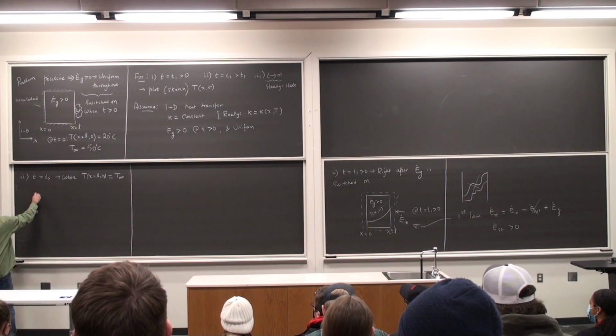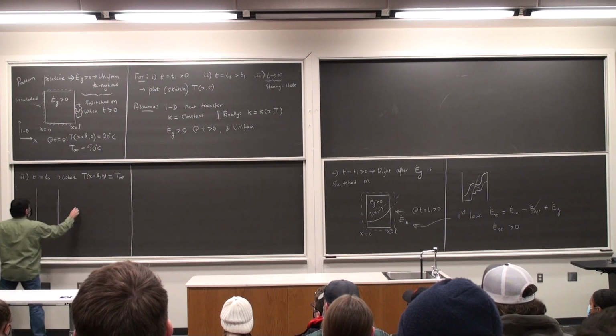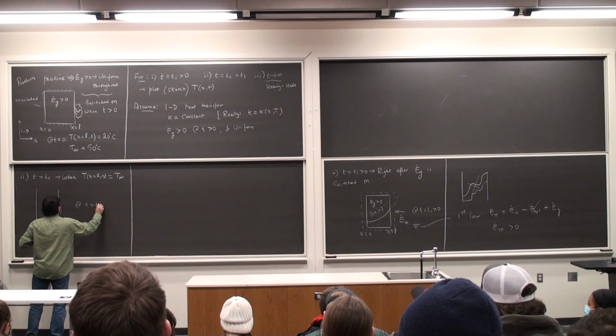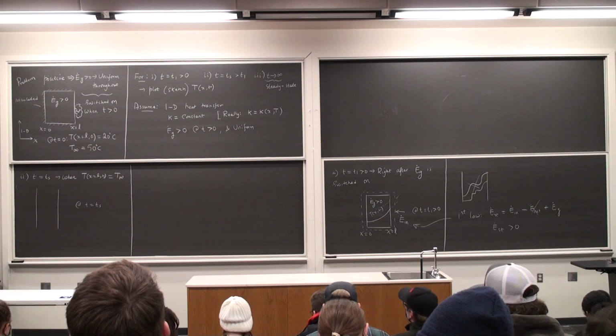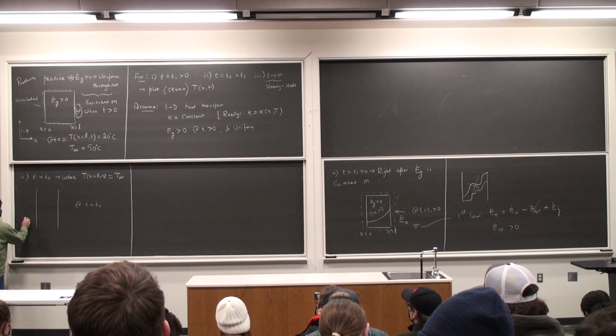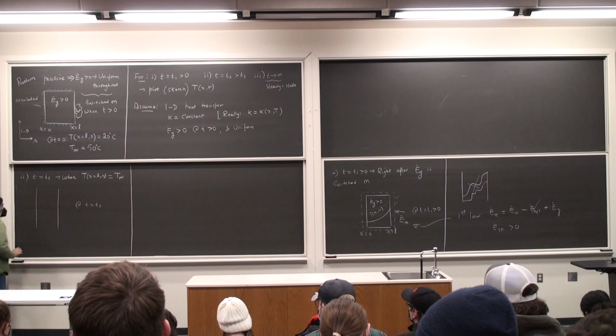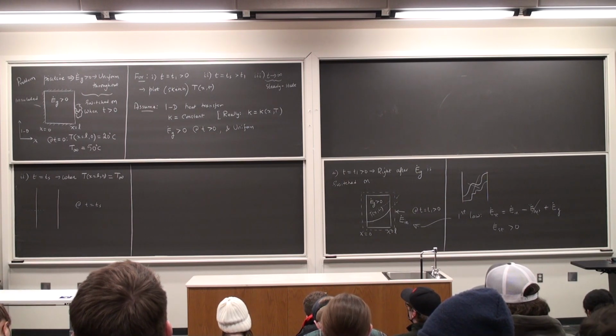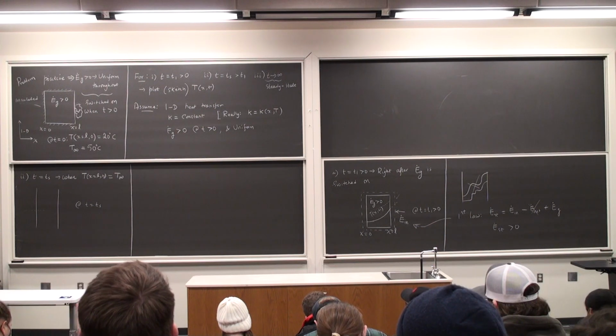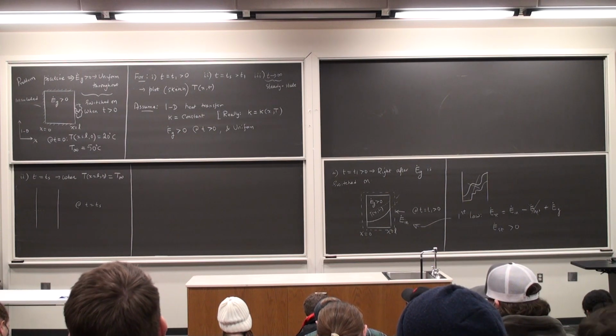If I draw this wall, this is at T equal to Ts. What should be the slope on the x equal to 0 side? Same as before. What should be the slope at the x equal to L side? It should also be 0.